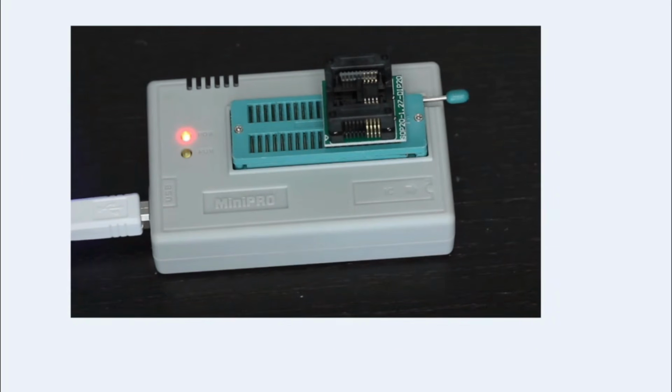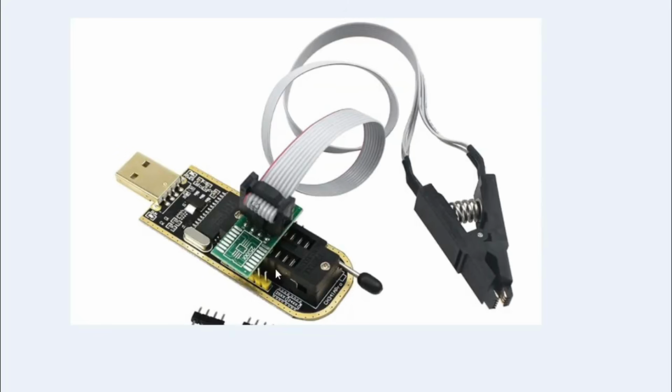But if you have a programmer like this that has the clip, you can program your BIOS without removing it from the motherboard. You can just connect this clip to the BIOS on the motherboard and connect this EEPROM programmer to the USB of the laptop and launch the software, and then you can program the BIOS. So it's pretty easy.